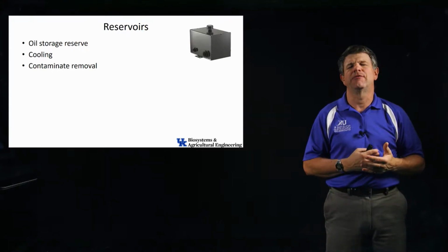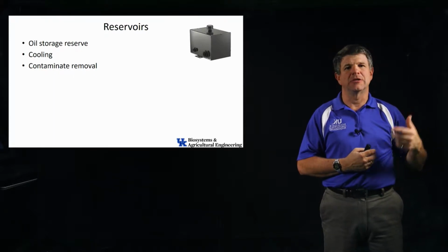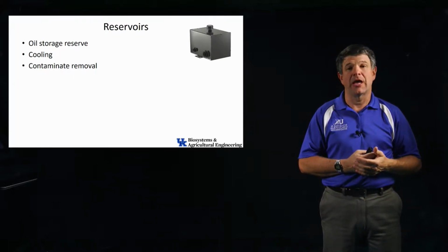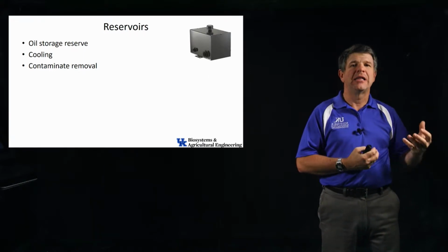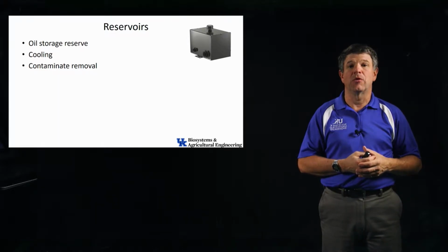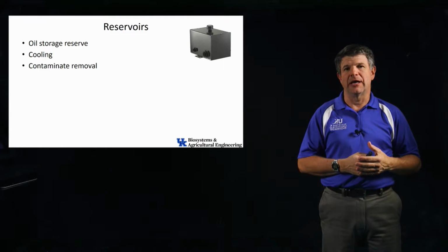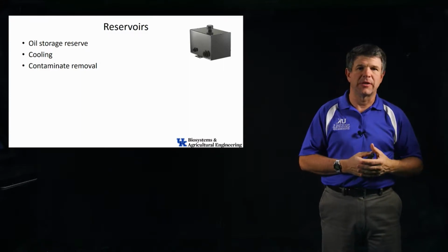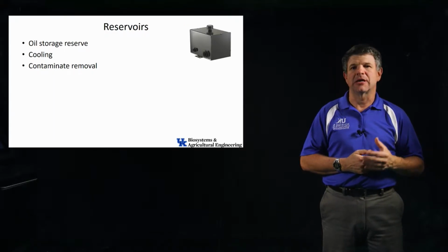But probably the other major function of a reservoir is for cooling. Remember, I talked about the fluid power systems. They're terribly inefficient. They can be. There's a lot of waste in them, so they build up a lot of heat. And that heat gets transferred into the fluid, and that ends up back in the reservoir. And so one of the functions of a reservoir a lot of times is for cooling, to be able to cool that liquid down, to dissipate some of that heat away. So we'll talk about design and how we do that in just a second here. I'll show you the equation.